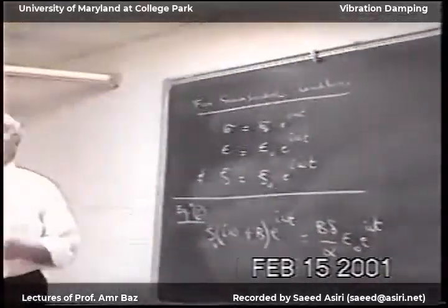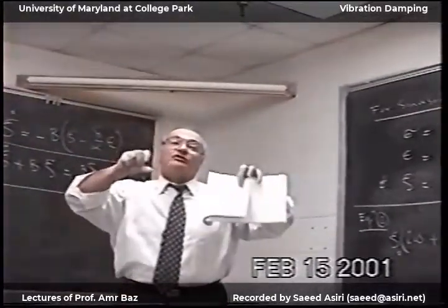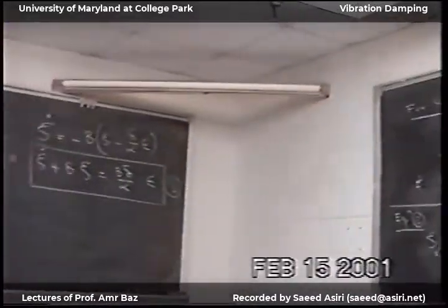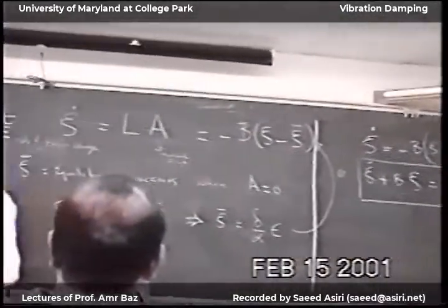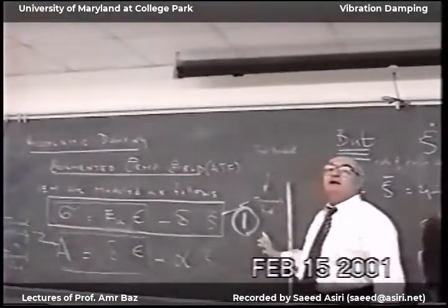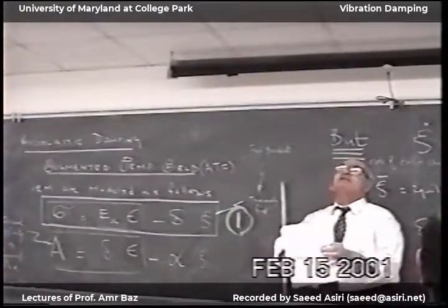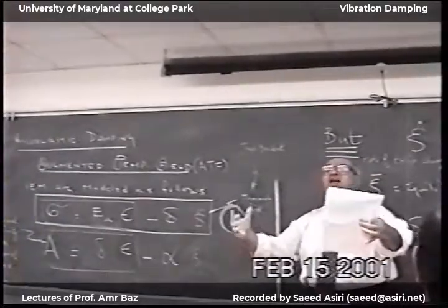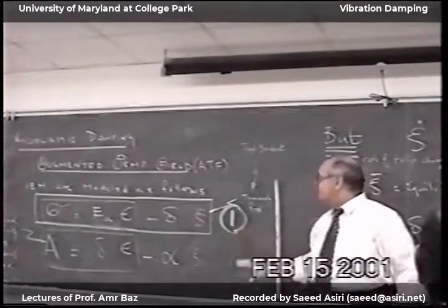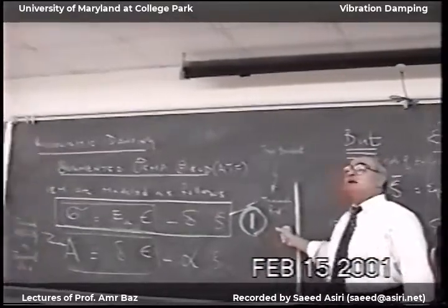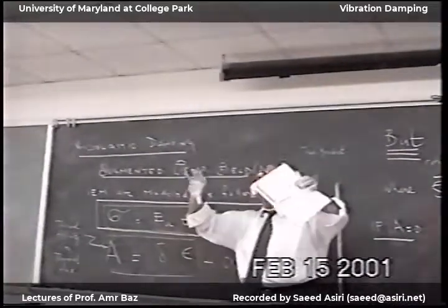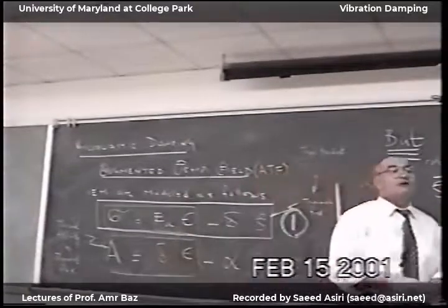Now the nice thing here is, if you have this viscoelastic material and you put piezoelectric powder inside it, then you can come to these two equations and add electric voltage. The viscoelastic material with piezoelectric powder is a very important coating for submarine hulls, or anything where you want to reduce sound radiation. So you can model it with electric voltage, thermal field, and strain, and this viscoelastic material will have all these parameters combined together.